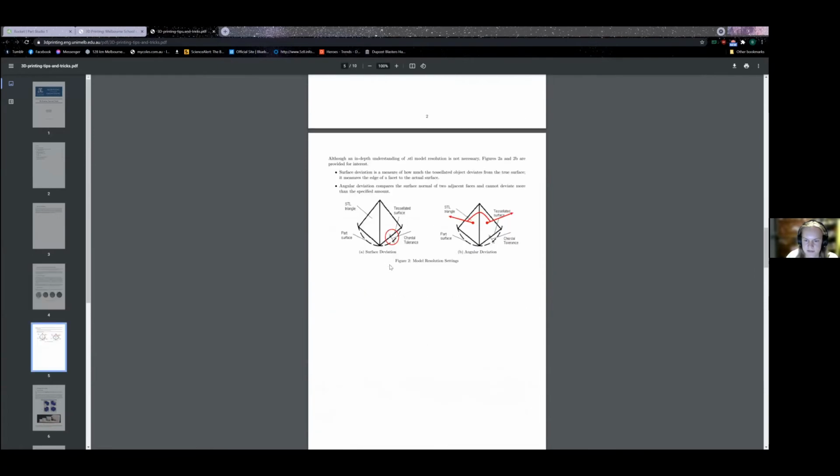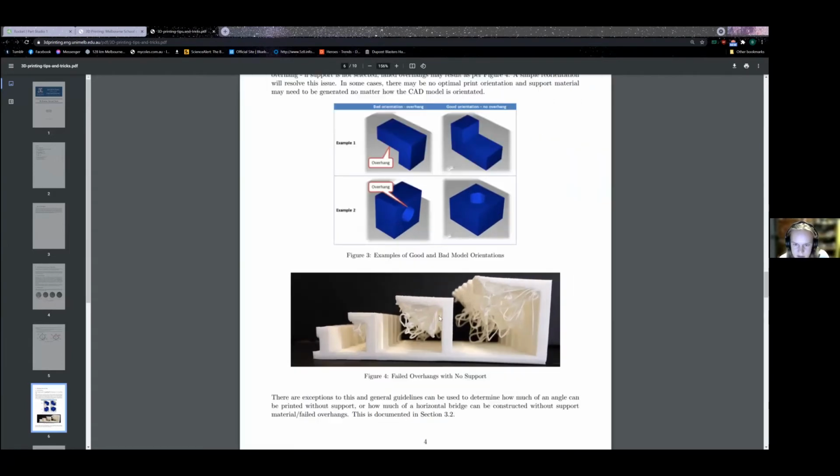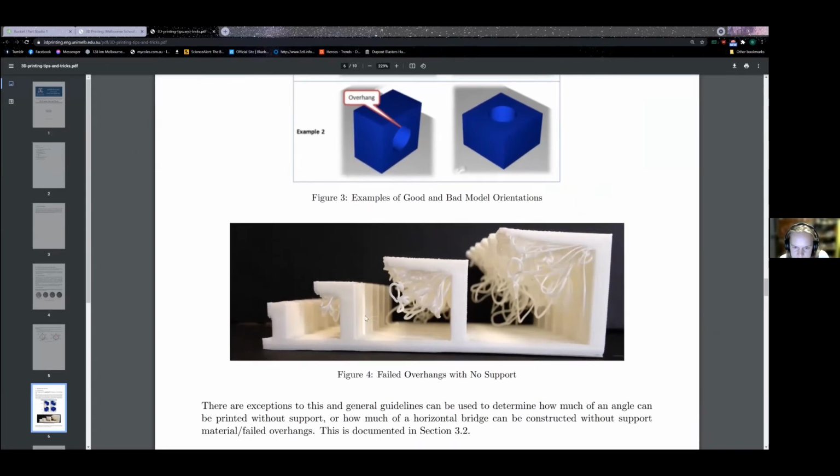a 3D printed part. So here you see the problems that you can get with a large overhang. I'll zoom in a bit. You can see a little bit here the layer lines, where the 3D printer has come along and done a new layer of plastic. It would have made this entire base layer, one layer on top of the other, and then started making up these little funky shapes. So it's done a layer here, then another one, etc.